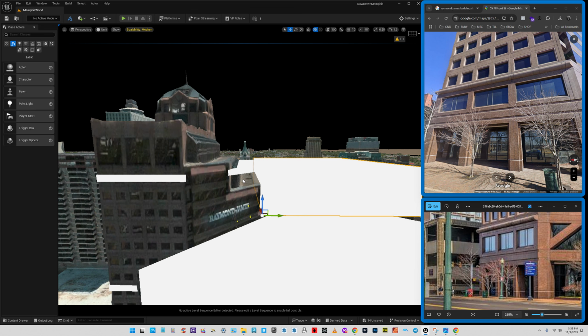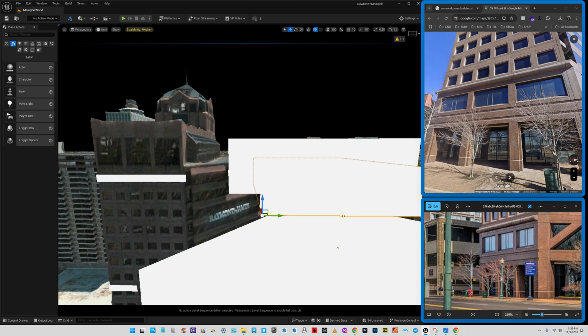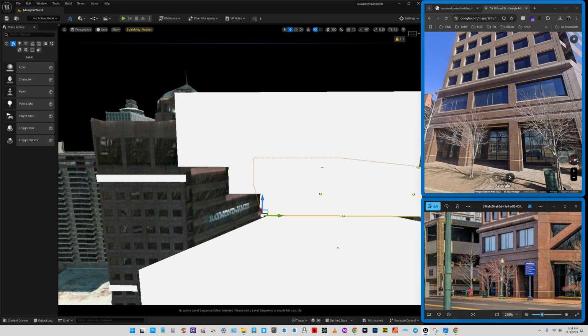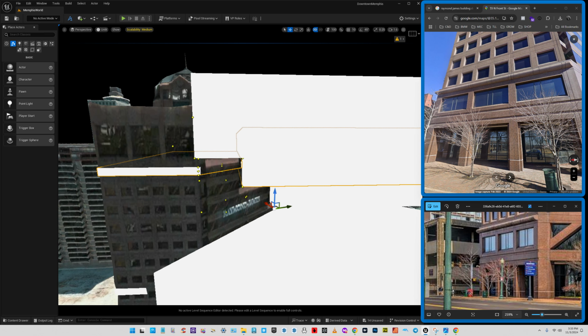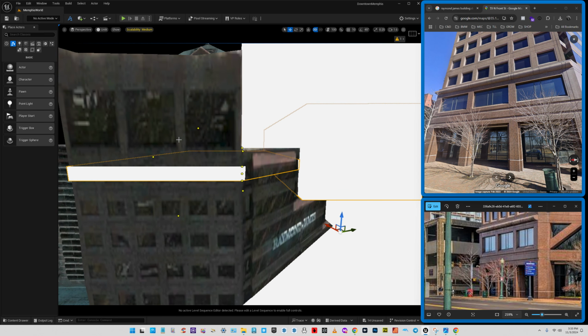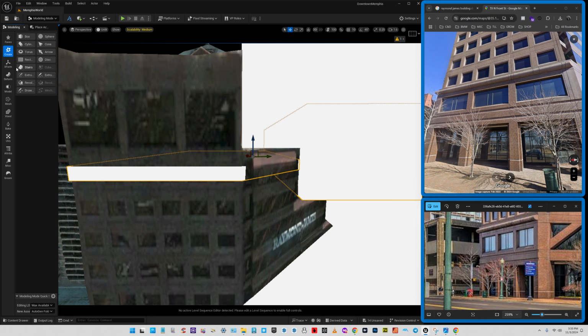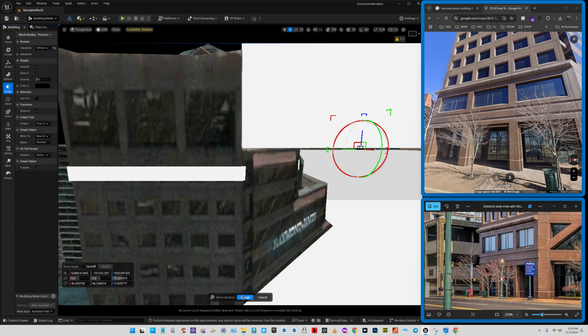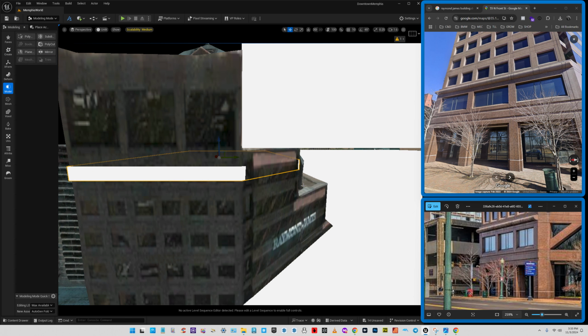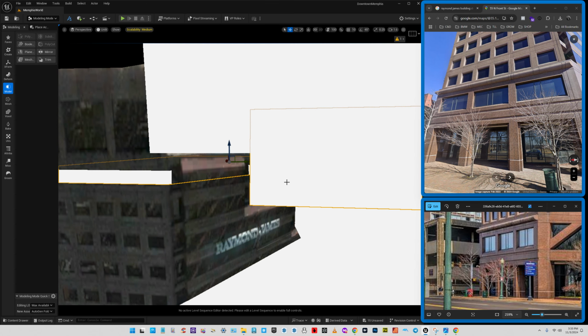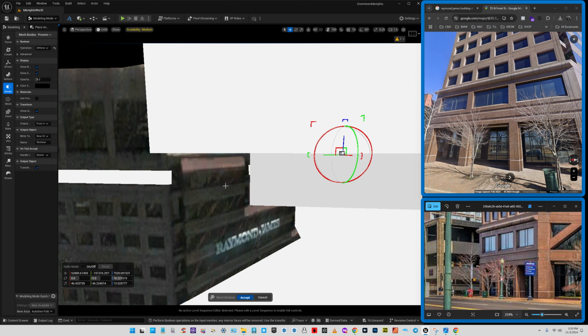Okay, there's our Booleans for that, and now I can turn those other Booleans back on. We're going to take this one and duplicate it and cut it out of this window piece. So modeling Boolean except, undo. I thought we duplicated this, but I guess we didn't. Let's do that again. Boolean except.